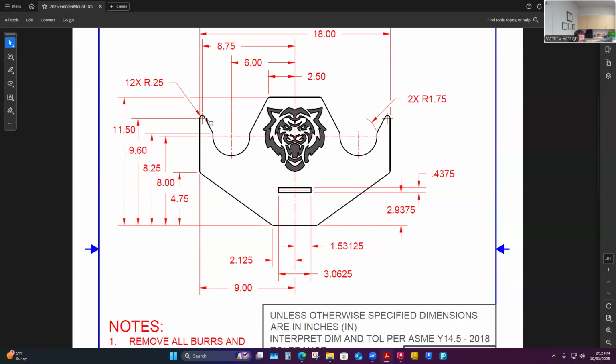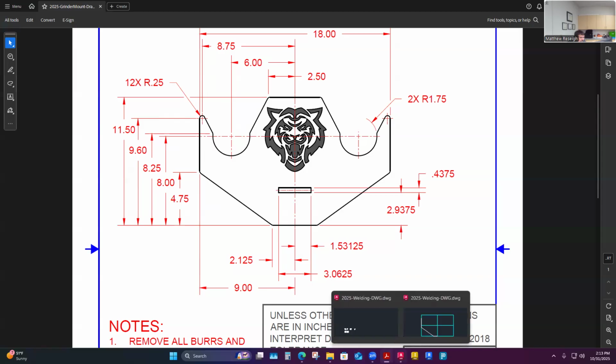I can for sure put in, so I can use the arc commands to do that, or what I do a lot for arcs is actually just draw the full circle and trim it to be the arc that I need. And so that's kind of where I'm going to head with this. Let me first put in the construction line center lines. So I'm going to put a line in that's up from the bottom 9.6 away, and one that's vertical from the horizontal midpoint of mine, 8 3/4. So let me put those two construction lines in.